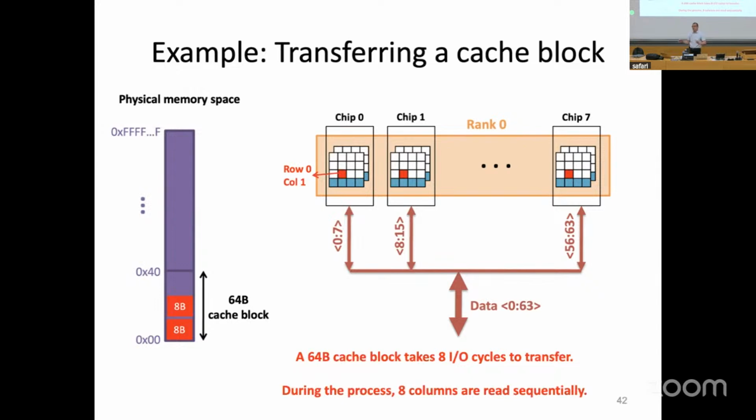I should also say that this is one way of designing DRAM. This is the common way in general purpose computing. There could be other ways to design, but if you look at DRAM today, HBM, high bandwidth memory, for example, LPDDR, low power DRAM, there are different kinds of DRAM, but all of them operate based on the same fundamental principles. At the core, the array is essentially the same. What matters sometimes is the interface. For example, how do you design the interconnects so that they're high speed or low power, etc. But these are below the abstraction level of this course. There are also architectural issues, but again, we cannot cover everything in this course.